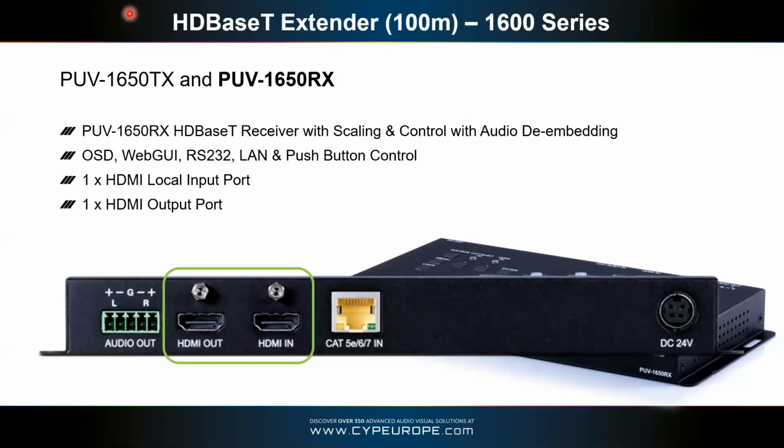So this local input is often used for those digital signage type sources, where you just have some digital signage of the company going through when there's no meetings going on in the room, or in an education environment, it might be the default PC with the website of the school or university in there. Commonly used there, and then there you can see the audio output. So again, you've got the plus and minus for left and right, and the ground if you want to be balanced, but you can just wire that as unbalanced as well.